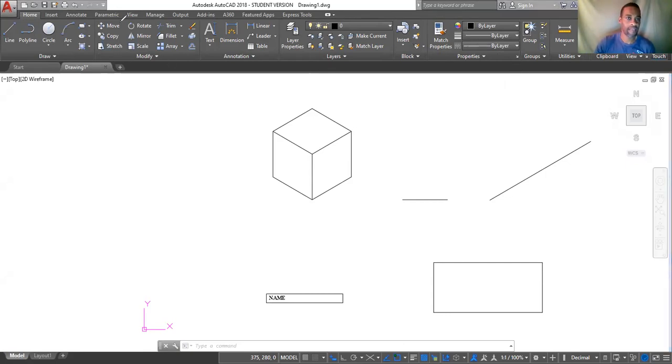And it's located here. It's the second palette on the ribbon, or modified command. The first one we'll be looking at is the move command. And it's important to know that for AutoCAD, we can either use the icon or we can choose to use the shortcut key or alias. Each of these commands has an alias.